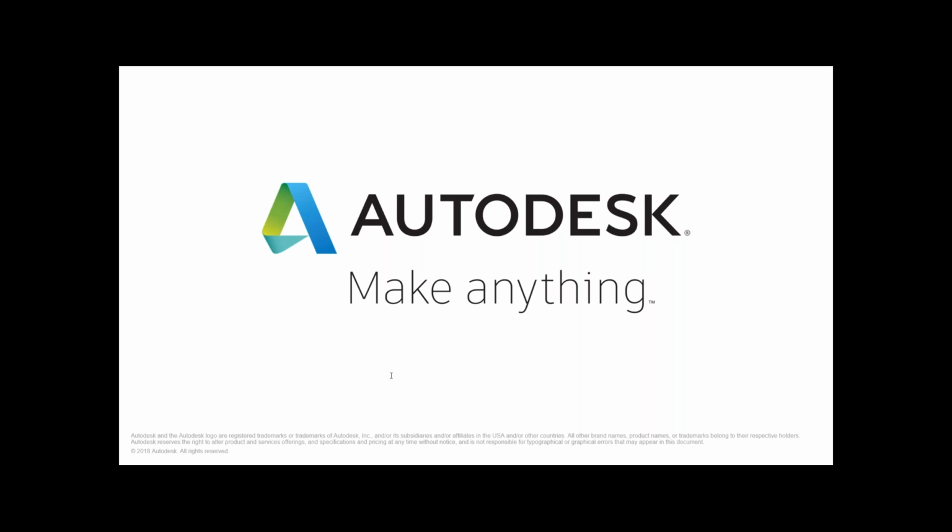David, just to add, if you have the AutoCAD toolsets, I think that's another advantage. AutoCAD Mechanical has a robust STEP file translator. You could use that to bring the file in, save it as an AutoCAD DWG, and bring it into Plant 3D. Even in terms of export, you can open the plant file in Mechanical, and then do a STEP out from AutoCAD Mechanical. Okay.